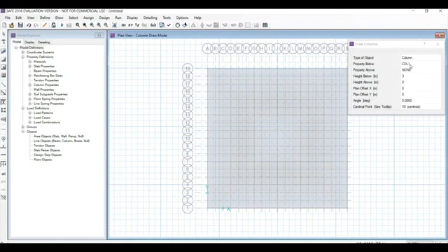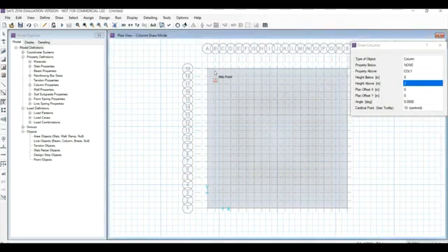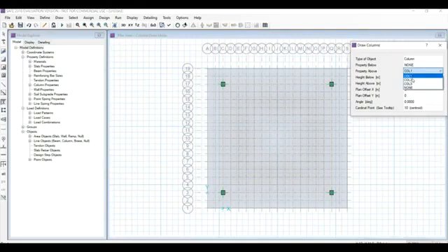Column 1, below is none. So make sure that below is none. Above is column 1. Height below is 0. Above is, let us assume 2 meters of plinth beam level. Then go for 2, and then draw the column. Column 1. Let us assume that there are columns at 2 meters distance from each and every center. Column 1 is completed. Now draw column 2.